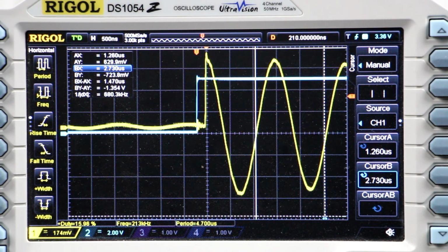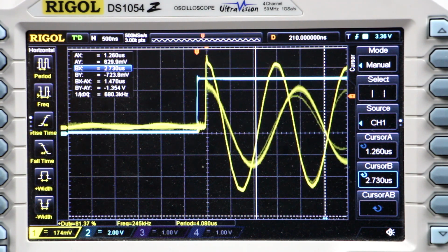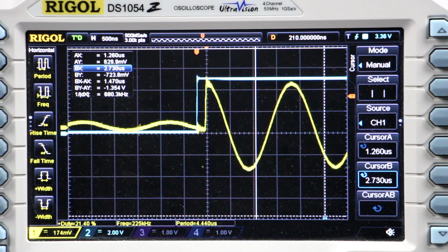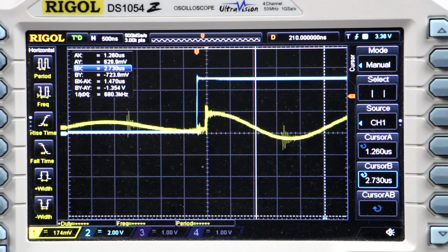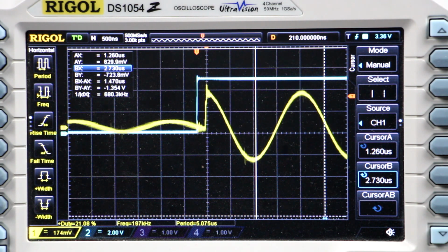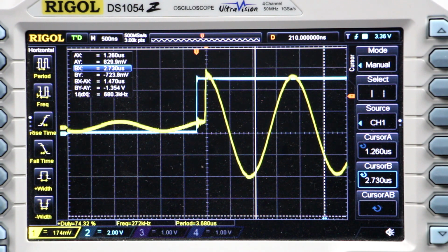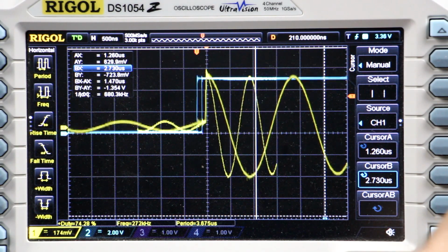So, quite simple. If we know that the resonant frequency of a tank circuit is determined by the inductance and the parallel capacitance, well, we simply can put another parallel capacitance. In this case, I've taken a variable capacitor and I connect it exactly at this moment, and you can see the frequency has gone up. And if I change the value, the frequency goes lower and lower. And so with just connecting either a fixed or a variable capacitor in the right range to our coil, to our inductance, we can simply change the resonant frequency and measure now the Q factor, which surely has changed,